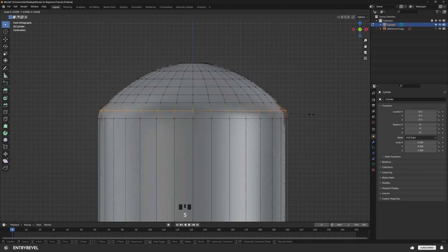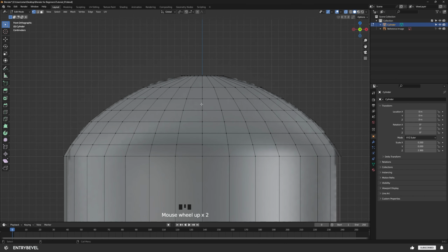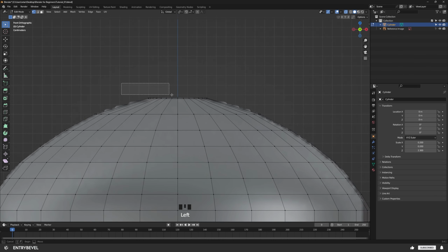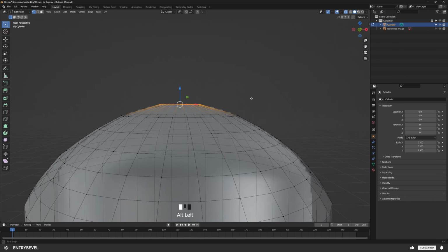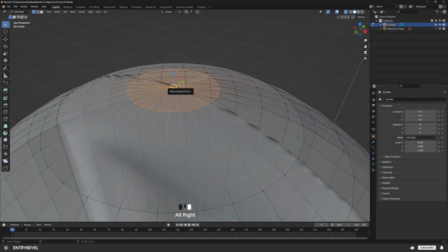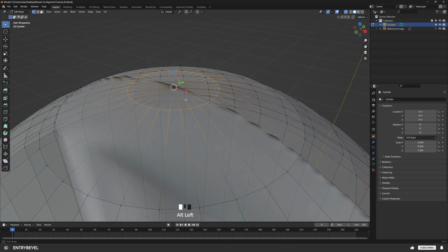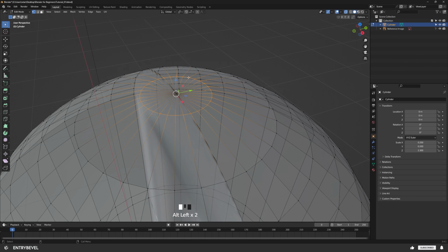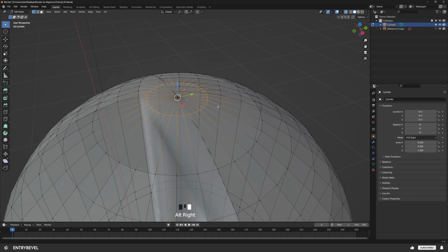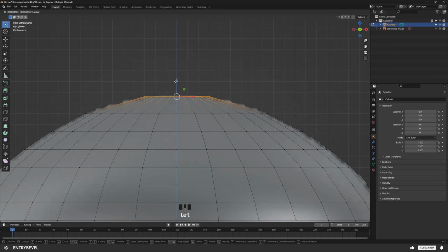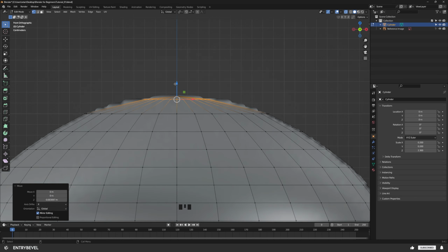And finally, these guys. The top is actually curved all the way, but ours is flat. So let's adjust the top. Select all of these guys, go back into our perspective view, and shift click on the middle here to deselect that vertex in there. So we have just selected the outside ring, not the point in the middle, right? Let's press tilde and go back to our front view, and let's drag these guys down.